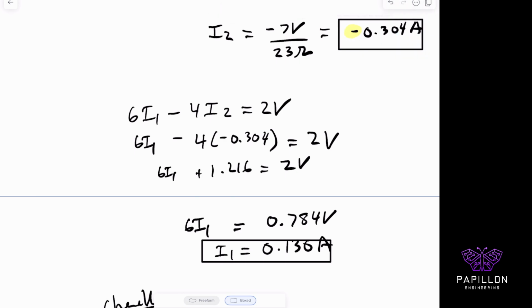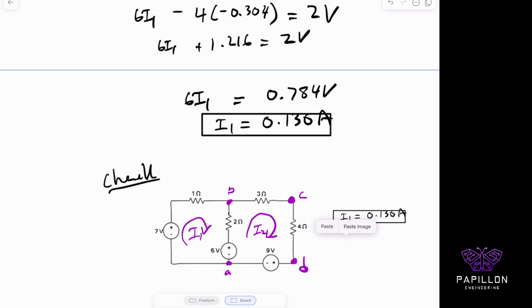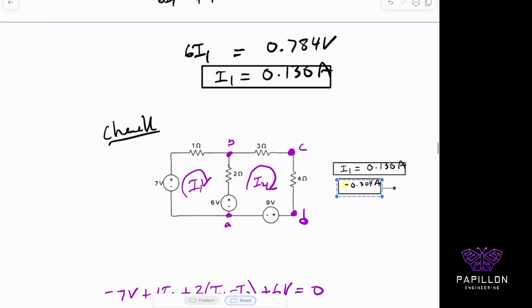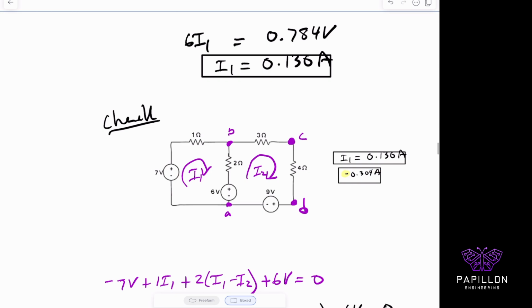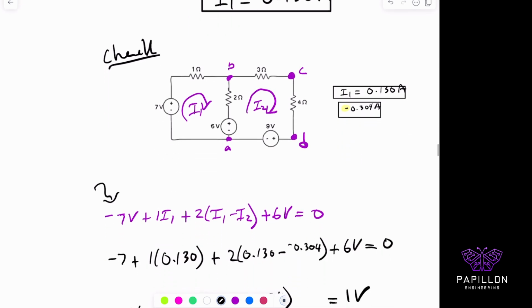You can see how that affects the proof in a moment. We're going to grab any of the loop 1 or loop 2 main equations. If I grab loop 1's equation, here's loop 1's equation over here, and I now substitute in my value of 0.130 for I1, times 1 ohm times 0.131 gives me a voltage for both combined.